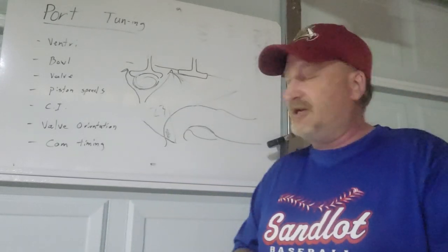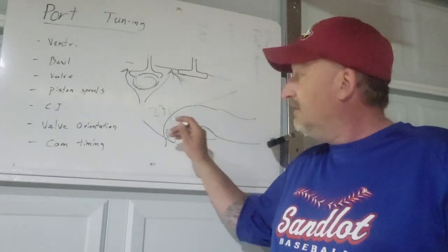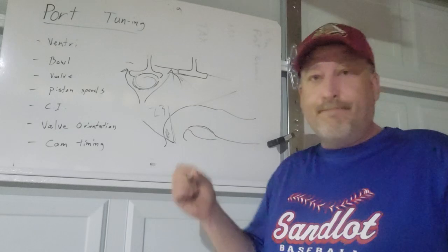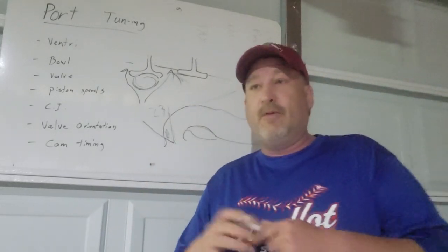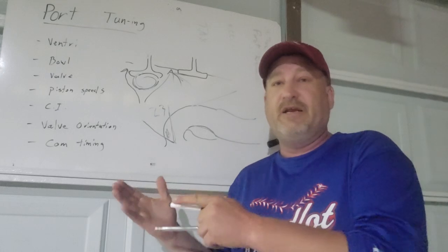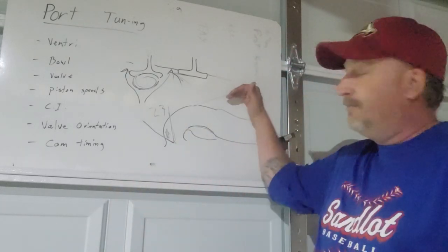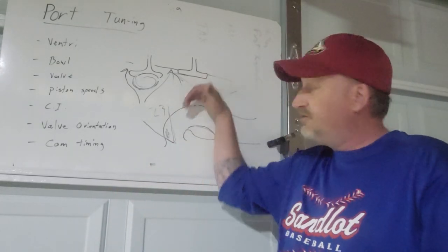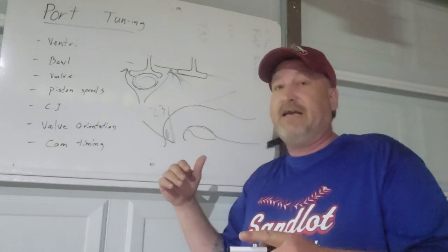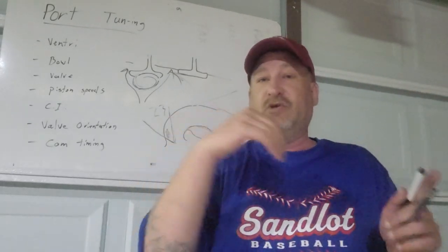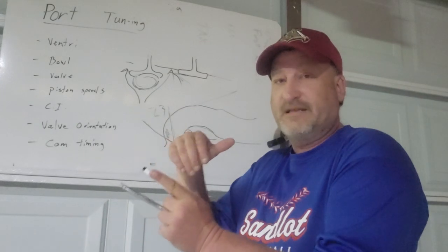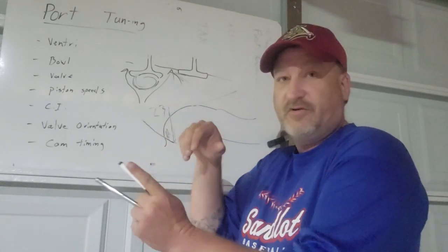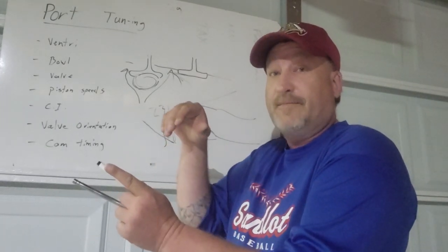Typically, the relationship between the port angle and the valve angle are married. So again, the small block Chevy has a 23 degree valve angle, but the port orientation to that angle is the exact same as the 18 degree small block Chevy. So even though the valve is canted over to the 18 degree from 23 degrees, the port is also up a little bit more.